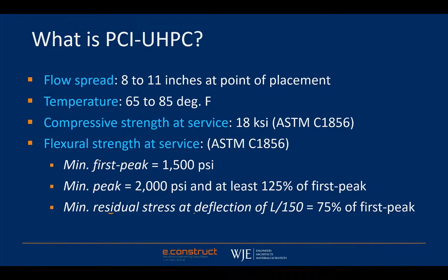So at the beginning of the presentation, I mentioned that we've kind of coined this term PCI UHPC. And the key in our minds here is that this is a type of UHPC optimized for precast, pre-stressed concrete. And by optimized, I mean that we have placed the focus on the performance attributes that are most important for this type of application. So the requirements fall into 3 categories. The first is some fresh properties regarding flow and temperature. The second is the compressive strength.